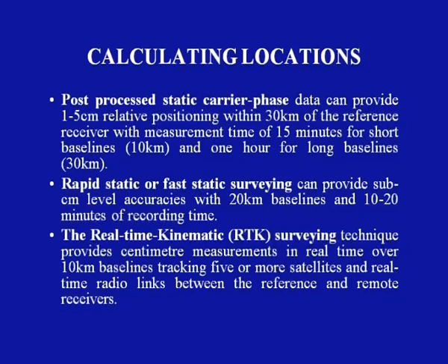First is post-process static carrier phase data, which can provide about 1 to 5 centimeter relative positioning within 30 kilometers of the reference receiver, with measurement times of 15 minutes for short baselines of the order of 10 kilometers and 1 hour for long baselines of the order of 30 kilometers.